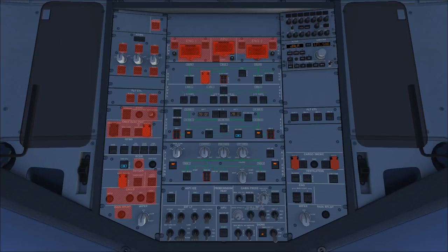And the purpose of the power transfer unit is basically to make sure that each of the 3 hydraulic systems have adequate pressure to function normally. So in the event that maybe only one engine is running or there's some sort of problem, the power transfer unit can transfer hydraulic pressure between the different systems to make sure that they're all pressurized and all working as expected.